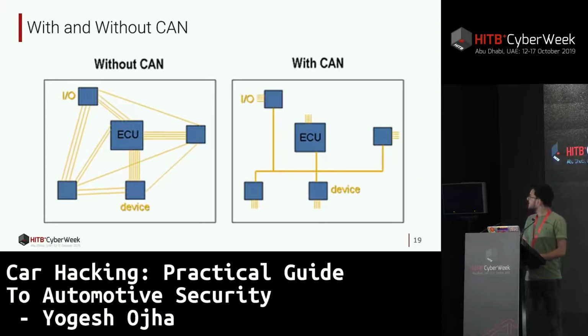So what if the CAN was never invented? Before the CAN was invented, automotive manufacturers used a point-to-point wiring system. It was working perfectly fine until we had many components. When I talked about just three components, the wiring was already messy. It had almost around 6 wires. So imagine with a hundred ECUs working together, how messy is the wiring going to be? It's going to be a real big wire bundle, right? So it was even expensive to maintain. So this was fixed by CAN.